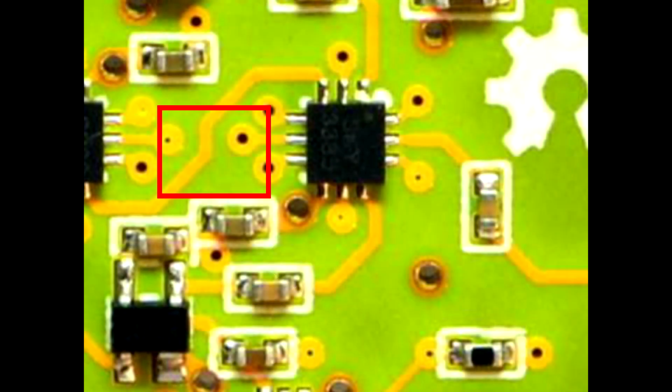Could you talk about the mitered traces? The mitered traces. Oh, the corners, how I use 45-degree angles. So that's more tradition than anything. There are some myths about signals not going through 90-degree turns. Don't worry about that.